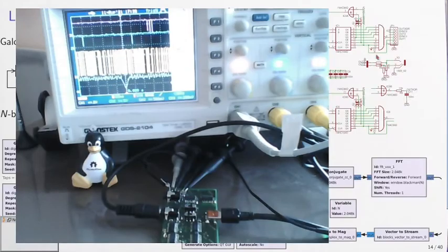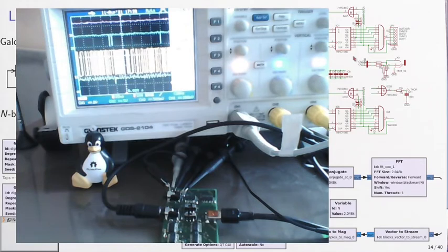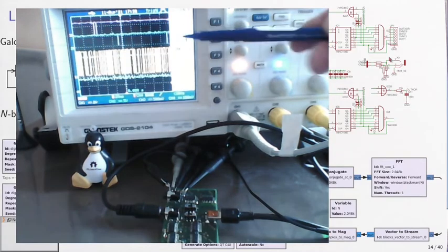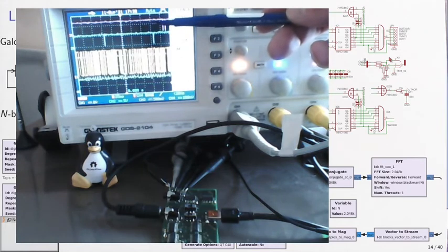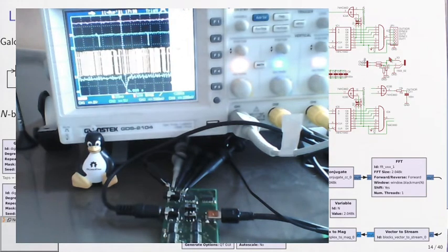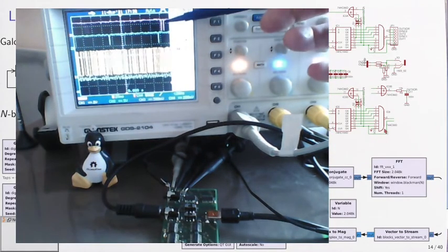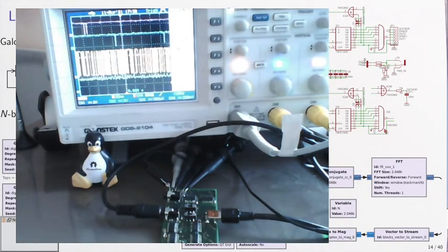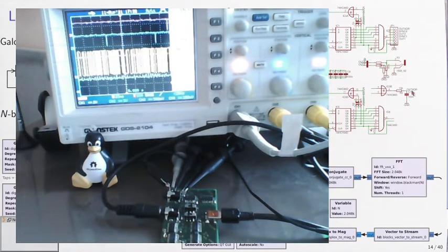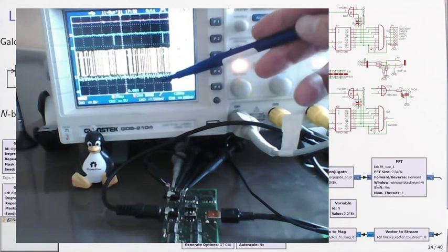So this all-NAND output over here is the trigger signal that is visible for the first pseudorandom sequence generator over here, and in purple on top is the output of the second generator, which is over here. So we see that these two trigger signals are drifting one with respect to the other because the two clock signals are slightly offset. And finally, we have over here the output of a low-pass filter, which is the blue curve here on the bottom.